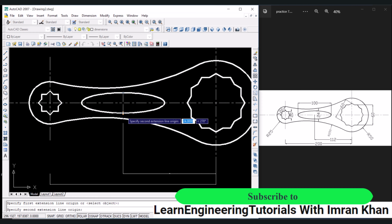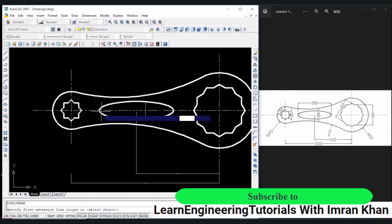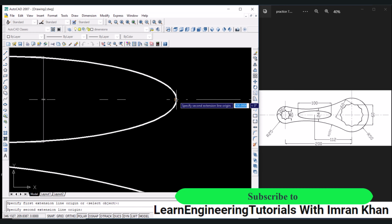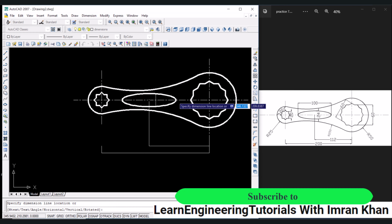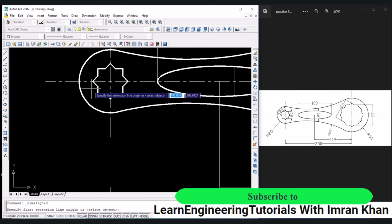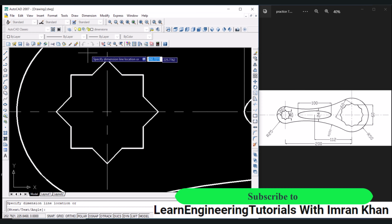click on this quadrant, click on the other quadrant, move the cursor away and click, press enter again, click on this quadrant, click on the other quadrant, move the cursor outside and click. Now click on dimensions, click on aligned, zoom in, click on this endpoint, click on this endpoint and click away.